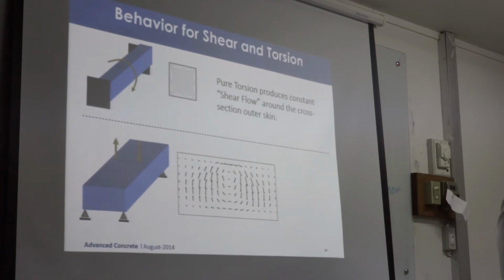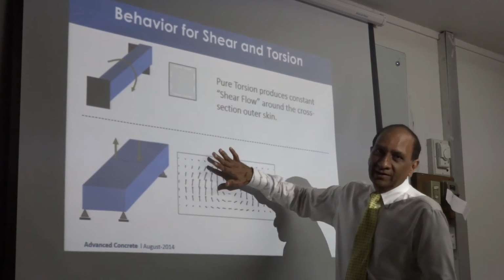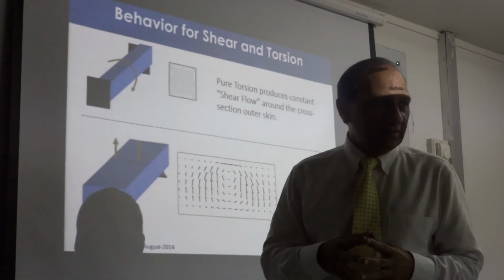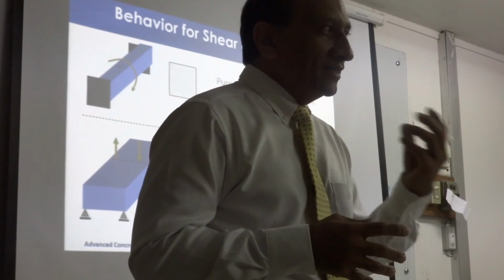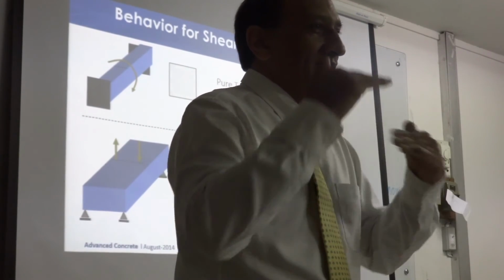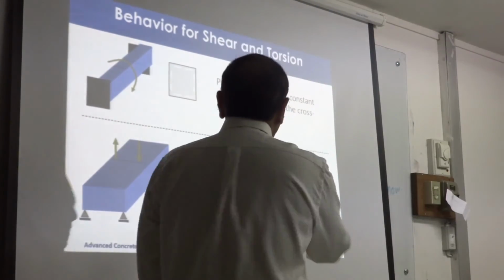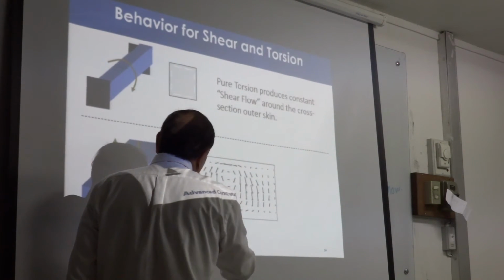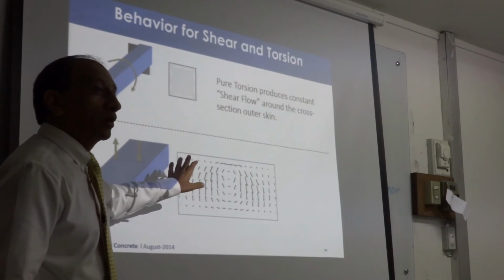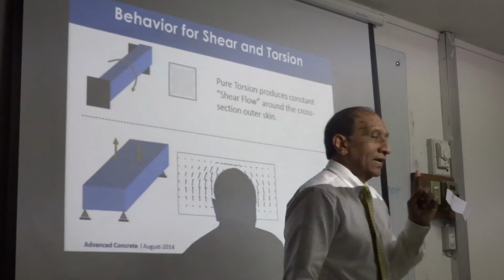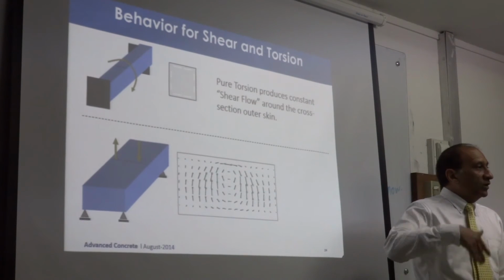And you also need longitudinal reinforcement going perpendicular to the surface for AL. So A, SVT and AL are calculated and provided like this, right? So you can imagine now this reinforcement and shear reinforcement must be added together. This reinforcement must be added together with the moment from bending or from axial load, from compression or tension, or bending about X or bending about Y, right? So this reinforcement can have many purposes depending upon how many actions are there. So the total reinforcement in a section could be like this, taking into account all 6 actions.